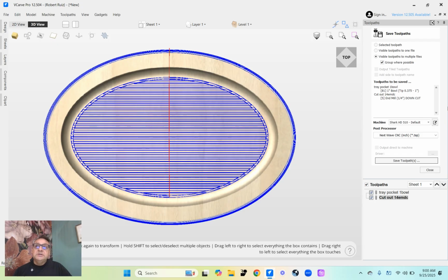In this case, you're removing a lot of material from the center. I think it's best if you leave your material connected to your table for as long as you possibly can, and make the cutout of whatever piece you're doing the very last thing. Okay. It just helps to keep your material stable on the bed as your router is going back and forth.